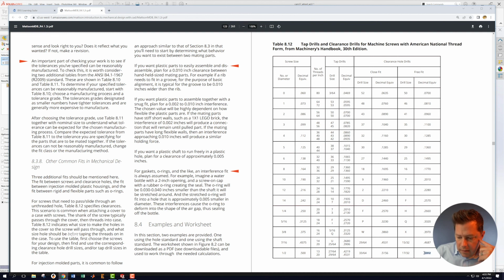So the answer to this is that the holes should be 0.5312. If that is the size, then we have a nice free fit for those lug bolts to pass through the product. Okay, that's it for the test. We are done with that. If I were taking the test and turning it in, I'd have to make some screenshots, save something as a pack and go and get that put in. But this is the test.